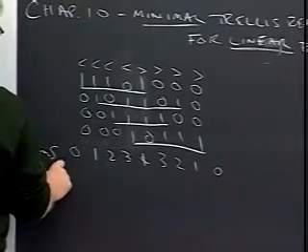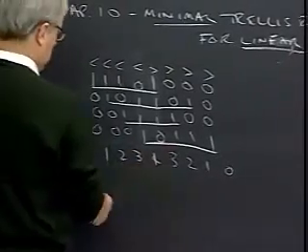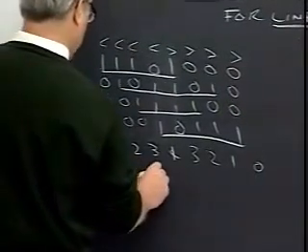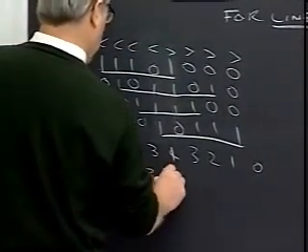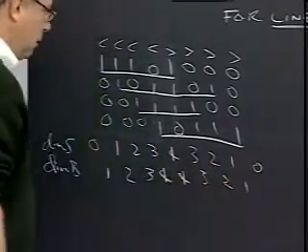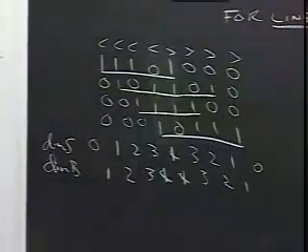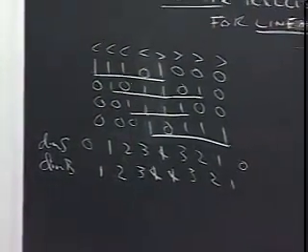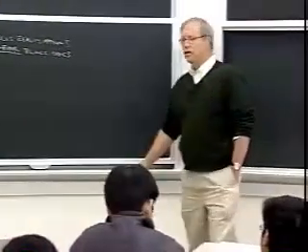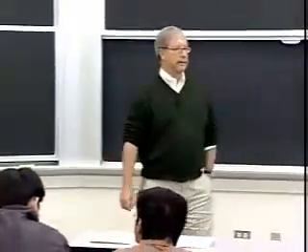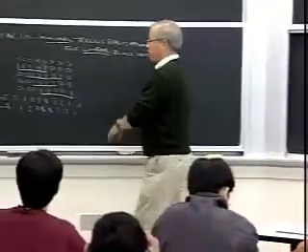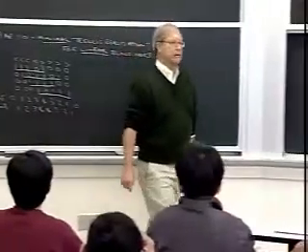If we look at the dimensions of the branch spaces, which I'm arguing is more fundamental, then we get 1, 2, 3, again, 4. So the branch complexity is now 16 rather than 8. It's going to be more difficult, definitely, to decode this code with a Viterbi algorithm. This is a more complex representation of an effectively equivalent code. Well, so this is a bad permutation. This is something I didn't want to do.